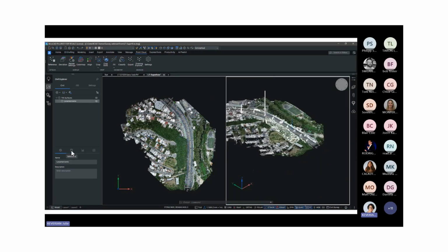Now, once we have the tin surface, it can still be edited. We can go in and remove the outer edges and some points. We can do some smoothing to clean it up a bit. So, it's pretty interesting that they were not able to really use a point cloud that they had and generate that tin surface in their other product, but we were able to do that very quick and very easily and give them all the information they need. So win for us.